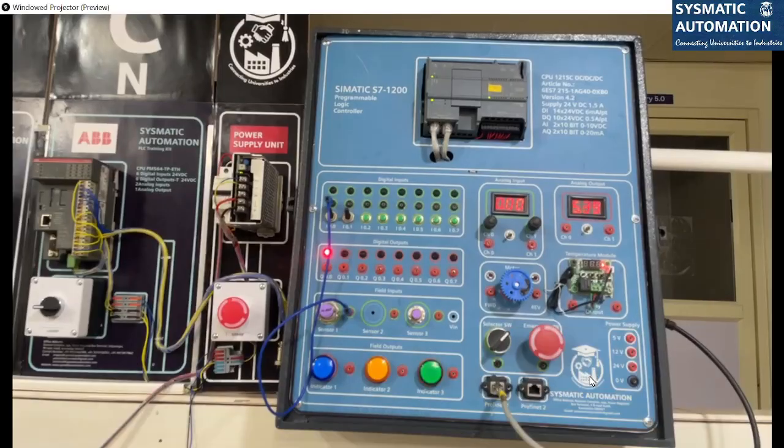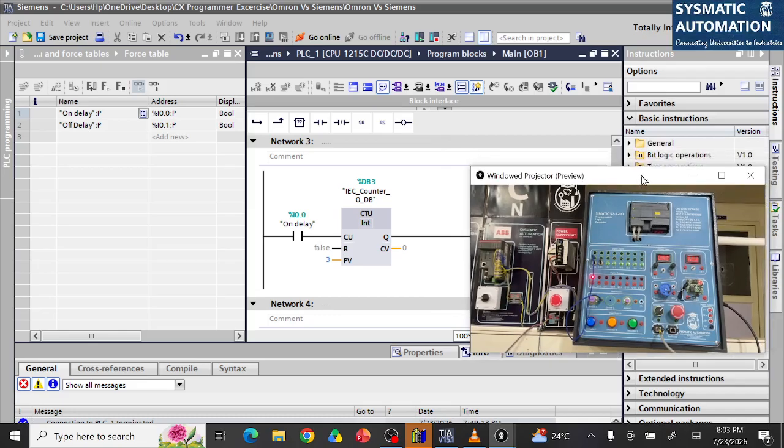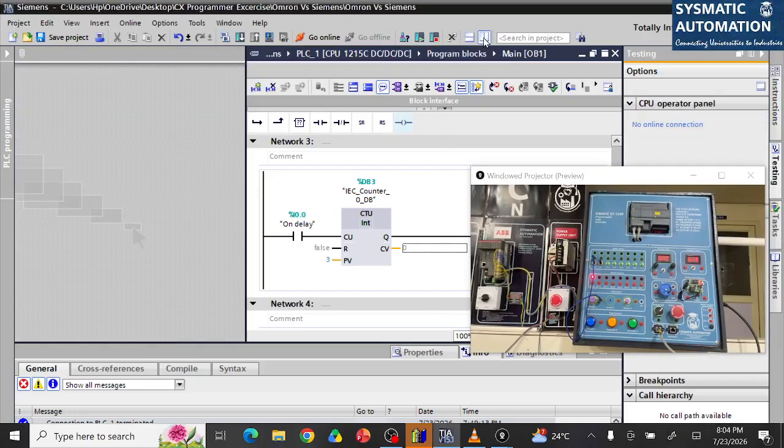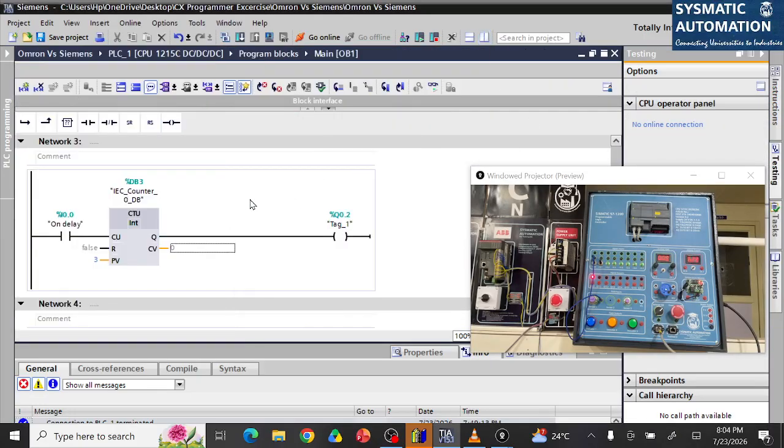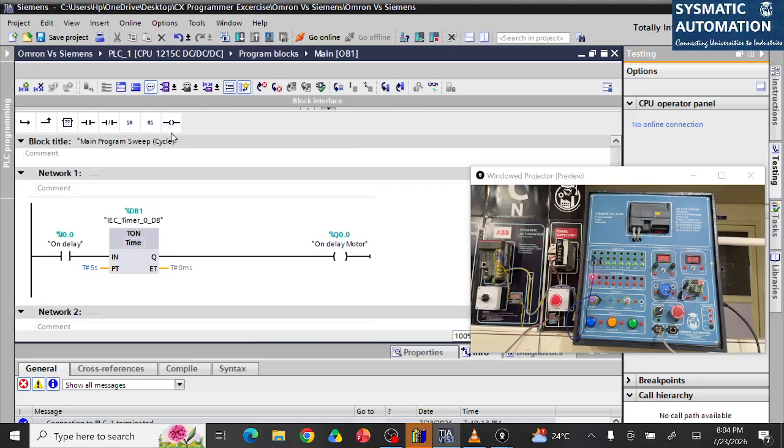Alright, so what we will do, we'll go to Siemens PLC now. So this is my Siemens PLC S7-1200 PLC with inputs and outputs. Everything you can see it here now. So going to the program now, TIA Portal. So now I'm not working with the simulator. What I'm working with is my actual inputs and outputs. So for this, I'll have to download this program into the PLC.